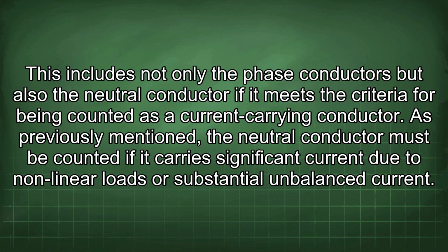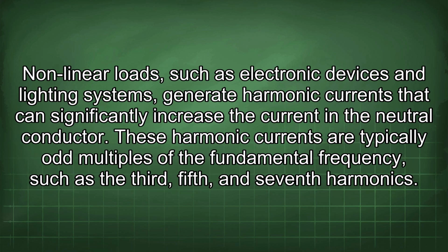This includes not only the phase conductors but also the neutral conductor if it meets the criteria for being counted as a current carrying conductor. As previously mentioned, the neutral conductor must be counted if it carries significant current due to nonlinear loads or substantial unbalanced current. Nonlinear loads, such as electronic devices and lighting systems, generate harmonic currents that can significantly increase the current